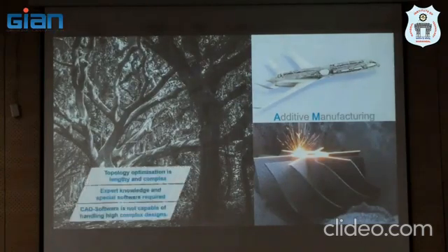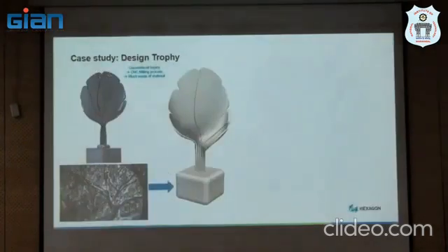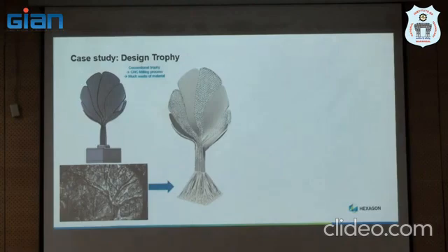So then we have to use the same. This is a conventional design. Now he said, let's replace it with this tree root structure so that I don't require any additional material. There are no printing related challenges, so it can be printed easily. We have done all of this, and it can be done in Apex generative design. This is a tree root which we used for 3D printing. This design doesn't require any support because it itself acts like a support.